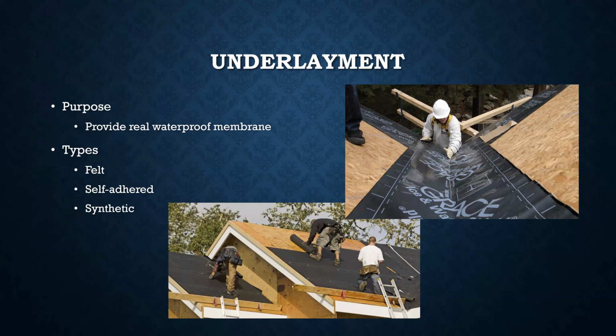The eave, the sheathing, the roof deck is cold. It's not part of the attic. So it freezes there because it comes back into contact with really cold air, freezes, turns into literally a dam of water, and then the water builds up on your roof and makes a pool. So if you don't have a really good substrate there, it's going to go right through any felt paper, any crappy underlayments. So you want really good stuff where ice damming is a thing. So yeah, the types of roofing underlayment generally are the felt, which is what you see in the bottom left. It's an older style. There's two types, 15 pound and 30 pound.